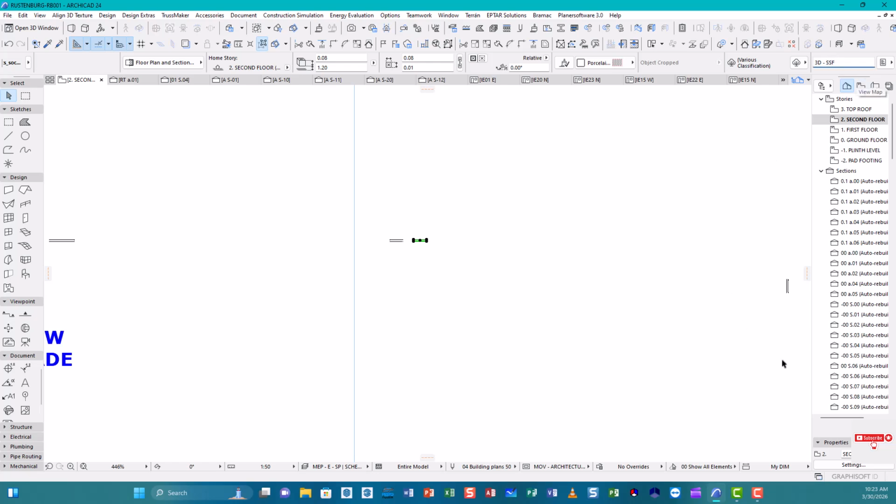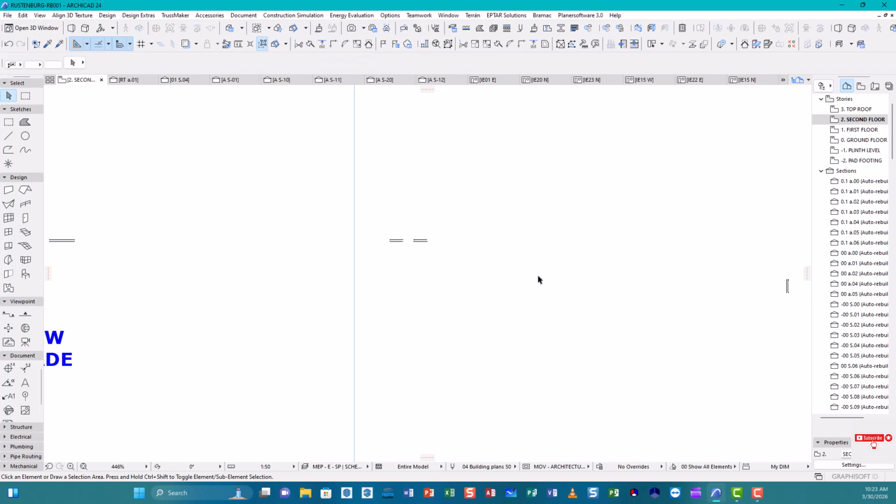I put an S there. One is a single port switch. The other one has to be a two-way switch. This is a single gang receptacle. So we almost have whatever we need to carry on.